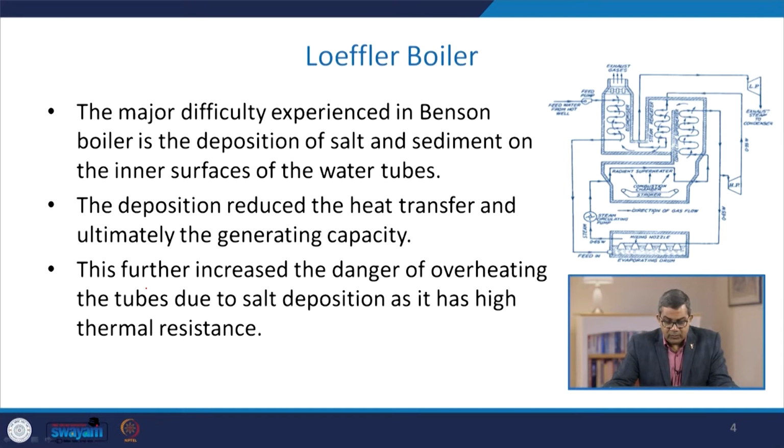Now if you recall, in the Benson boiler the tube's diameter was small. Sometimes that is advantageous, but any sedimentation, debris or salt may get deposited over a period of time, and then there may be a chance of choking.